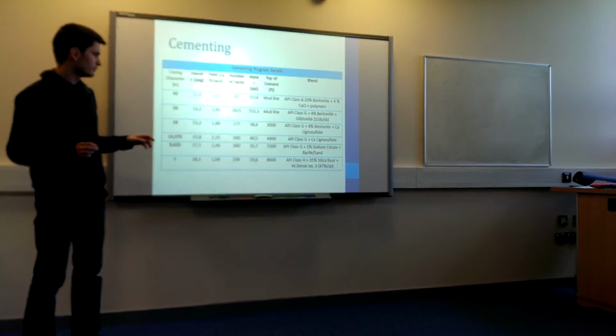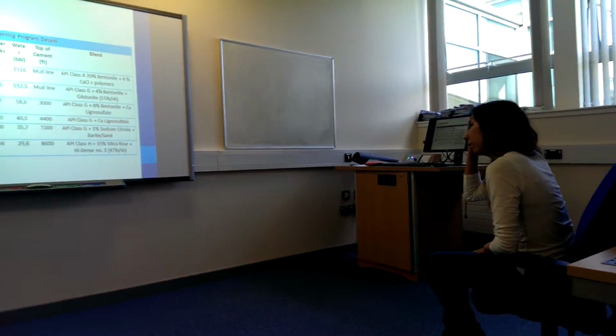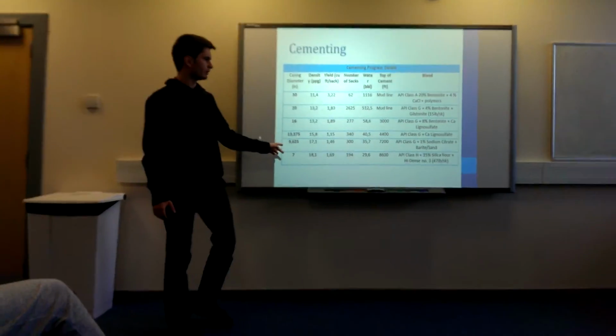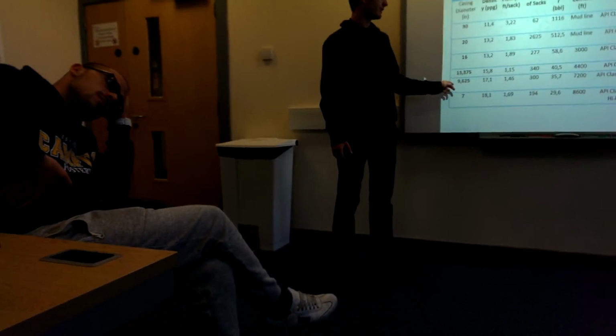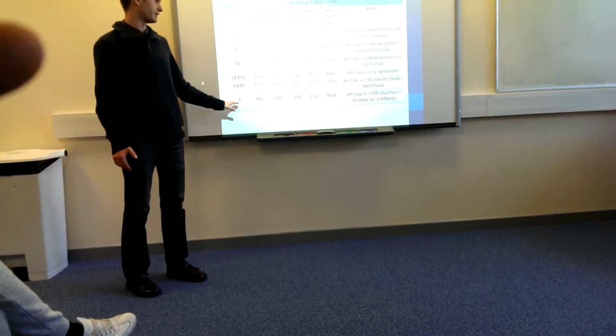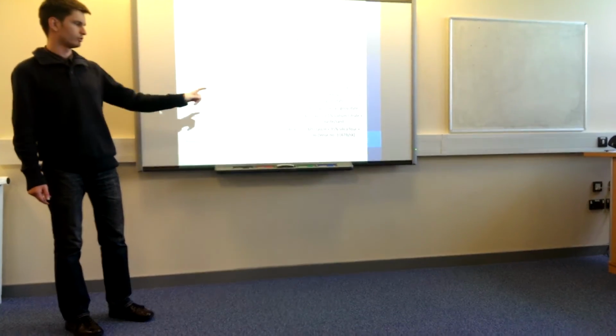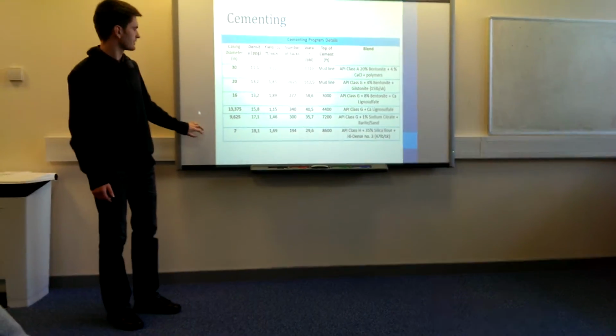Later we used much heavier cements because of the poor pressure gradient in the last 2 sections, and these cements were class G, and for the liner, if required as well. This decision will be based mainly on the assumptions which the cement engineer will make on site, and if we would like to cement the liner, it will be cemented with such a class of cement.